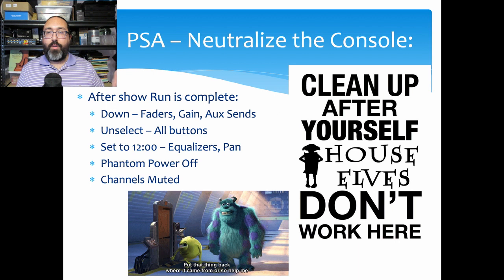Say it's just a bar one off, you're doing the band for one night, they're done, then you would neutralize that console. So, what does that mean? It's resetting the console to the original settings or putting that console back the way that you found it. Now, in some places, that means there might be a couple custom settings that you don't neutralize, and that's up to that place. Most of the places that I've been with an analog console, you're setting it back to factory resets. Now, for that, it means setting all your faders down, your gains all the way down, your aux sends all the way down, any of the buttons that you have on the entire console unselected.